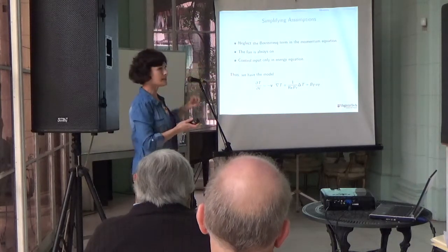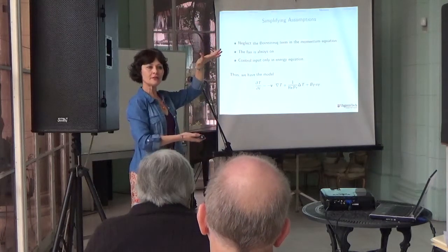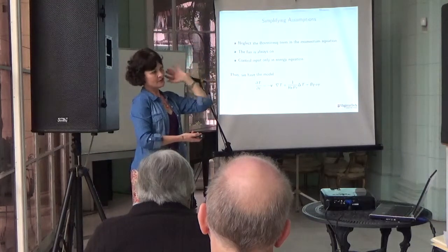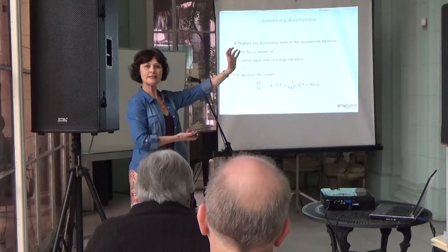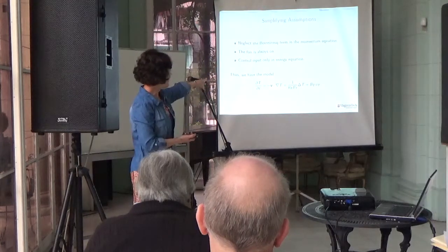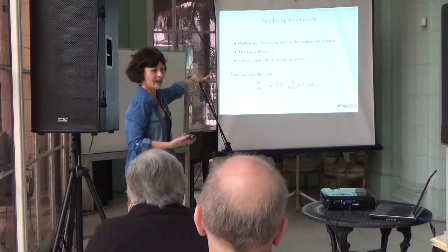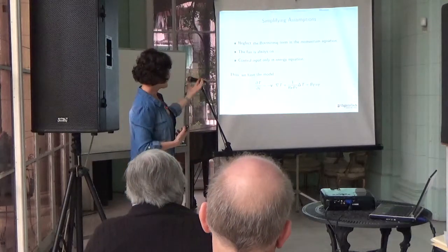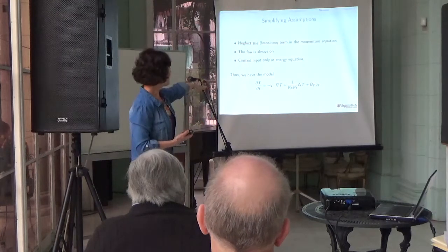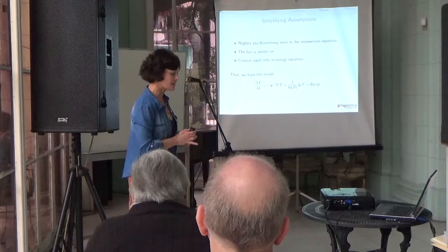So if I make these assumptions, I decouple the velocity equation and the thermal equation. So I can solve the Navier-Stokes first, independently. There's no controlling it. And then I can just plug it in here and only look at this equation. So that's a first try to see how one can do things. And so this becomes a linear problem. Velocity is known. So this is going to be our model, and the results are represented for this simple case.